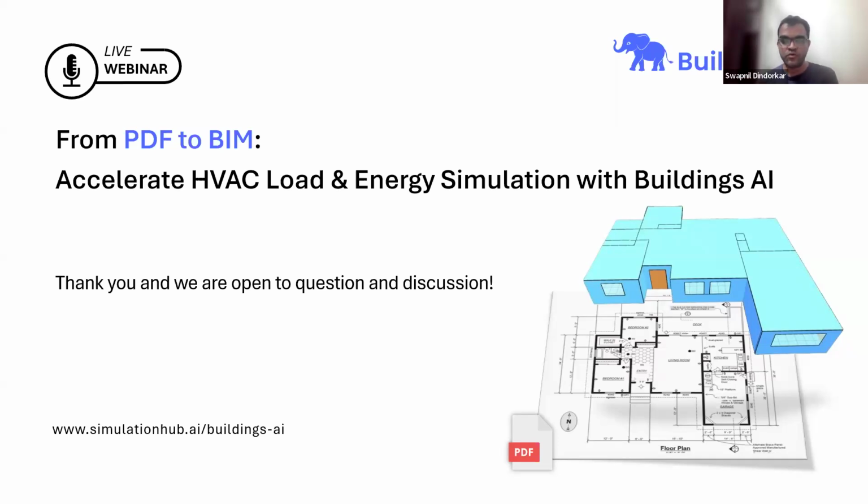Then you extrude them into FloorSpaceJS, give it as multiple floor layouts, and join them together into 3D. This entire workflow is still under development. The other one that is available right now is to export them as is, as different, disconnected layouts in FloorSpaceJS, and then post-process or modify each floor manually in FloorSpaceJS so that the 3D BIM model reflects that.